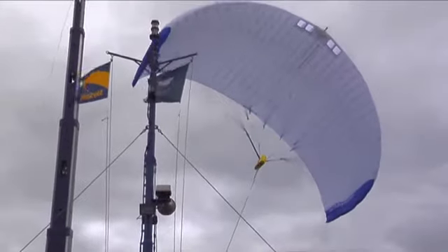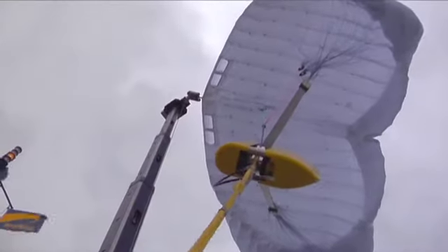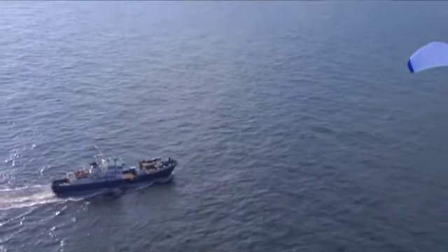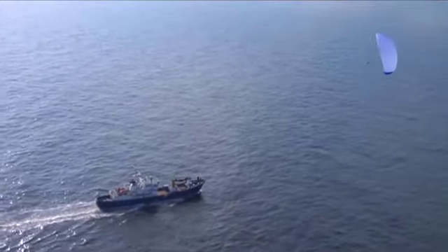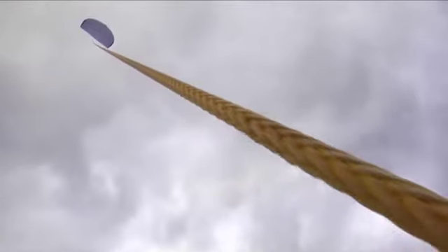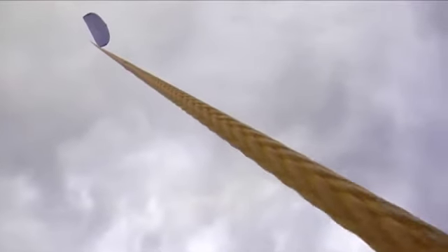I'm designing the control pod for our kite system. The control pod is important because it steers the kite, and the kite needs to move because it's very important that the kite has a certain forward force. So our kite is always doing a figure 8 in the air. It's possible to have a high speed, and if we double the speed we have 4 times the pulling force on the ship. All these forces are coming from the kite through the control pod and from there further into the towing rope.